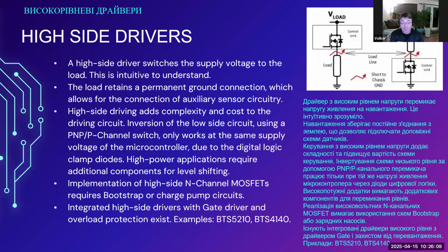That doesn't work because the voltage drop between base and emitter is always 0.6 volts. So if you're driving the transistor or MOSFET for that matter, from a microcontroller output, the voltage to the load can never be higher than the microcontroller voltage. That's not what you want.